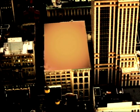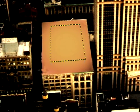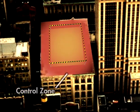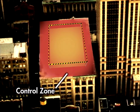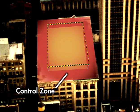A control zone is the usual method of fall protection used in industry, when other means of fall protection are not suitable or practical. The control zone is usually marked by a raised visible tape or some form of flagging. The control zone is the area between the marking and the edge of the working surface. There are clearly situations where the use of a control zone is not suitable. There are other situations where the width of this zone must be increased to be effective, for example, if the surface is slippery or the surface has a slope.